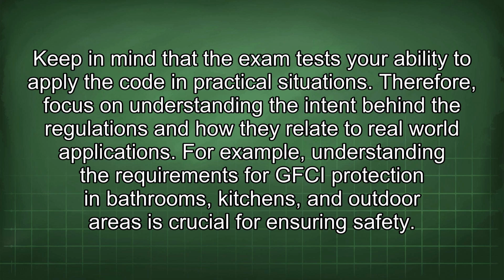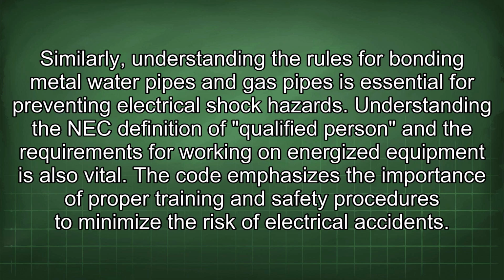Therefore, focus on understanding the intent behind the regulations and how they relate to real-world applications. For example, understanding the requirements for GFCI protection in bathrooms, kitchens, and outdoor areas is crucial for ensuring safety. Similarly, understanding the rules for bonding metal water pipes and gas pipes is essential for preventing electrical shock hazards. Understanding the NEC definition of qualified person and the requirements for working on energized equipment is also vital.